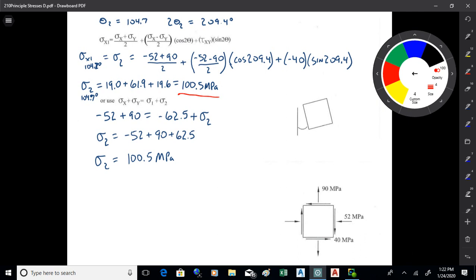So once you get those stresses on there in their proper orientation, which one goes where? I have that element drawn up. We could label that little angle there. You should be able to figure out which of the two that is. It's just a small angle there from the vertical plane going counterclockwise. So let's start with the angle. What's that angle down there? Yeah, 14.7. So where are these stresses going to go on that sketch?